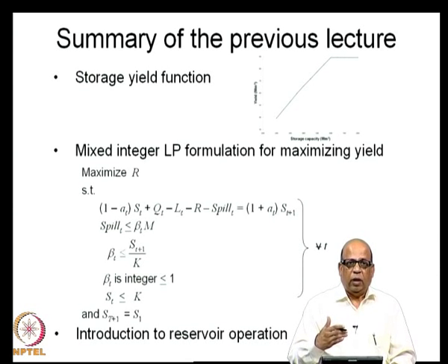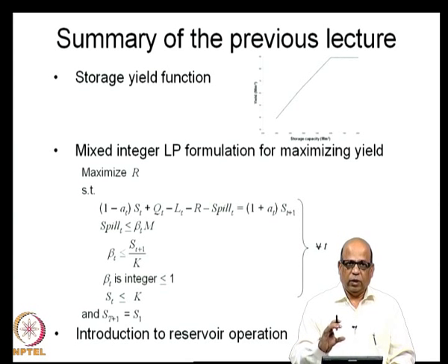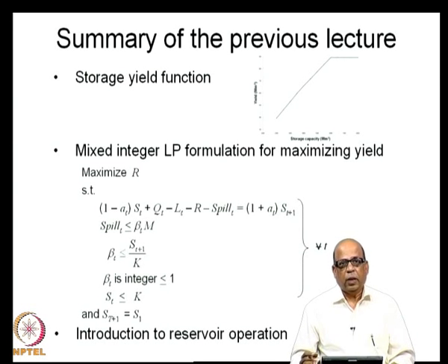And therefore, at the planning level, you plan the reservoir operation in a certain manner, keeping in view the likely inflow sequences that are coming in the year. So, typically we use the historical data and then derive the reservoir operating policies. By reservoir operating policy, we mean sequences of reservoir releases across time periods as a function of the state of the system.